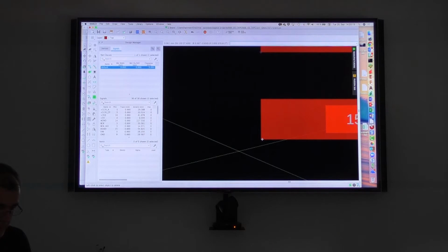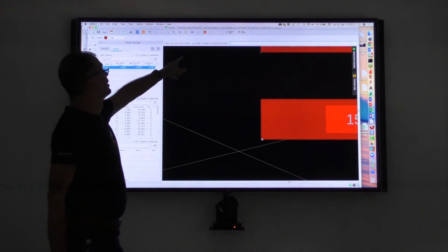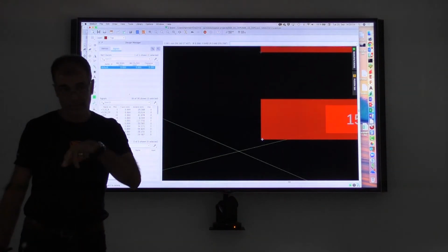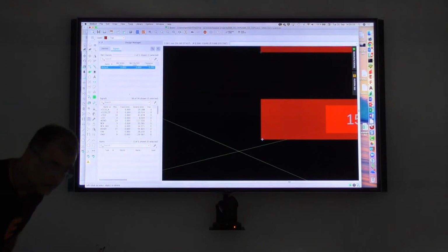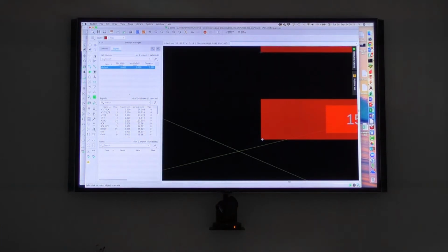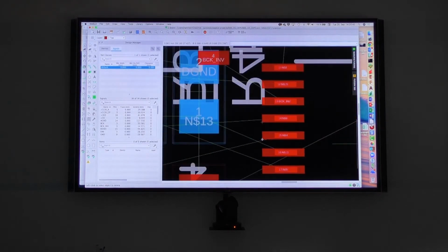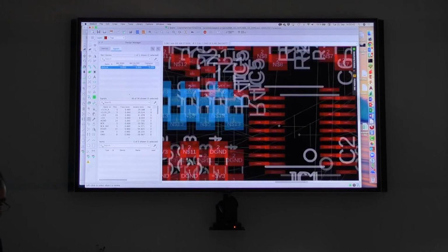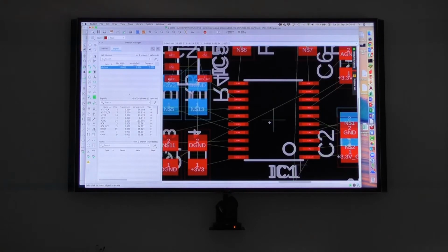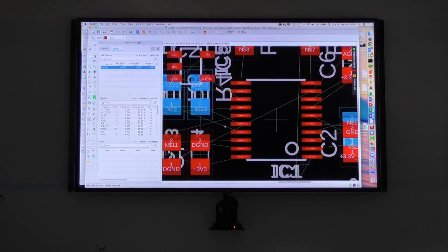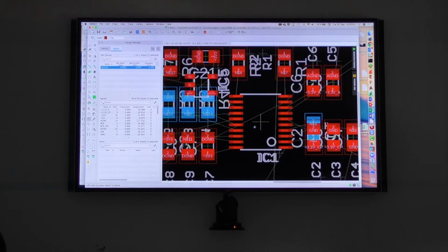Let's go there. Approximately. And you see in my relative coordinates here, it's okay, it's 0.65 millimeters pitch. That's what we have there. And so I can think about using this 0.65 millimeters to get out all of the connections from this component. So yeah, that's really craftsmanship. I don't know. It's something. Yeah, that's the challenge of layout. But I think that's just to show you what you have to think of.